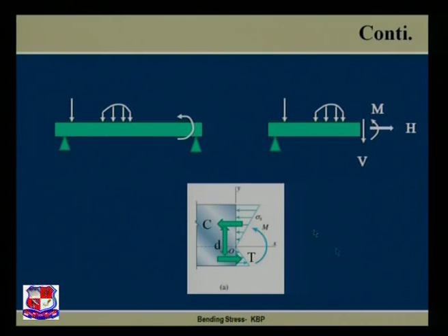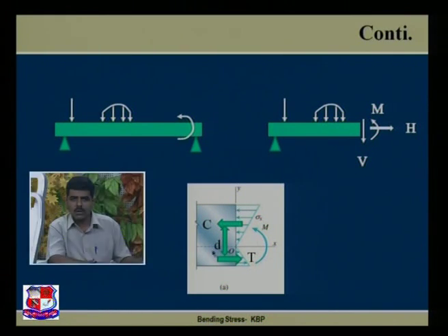If we take a particular beam, we subject it to external load. If we take a section XX over here, then this section divides the beam into two parts, the left part and the right part. At the section, each part is subjected to bending moment, axial force and shear force. The bending moment creates compressive force on the top region of a section, and the bottom region is subjected to tensile forces. This creates the bending stress in a beam.